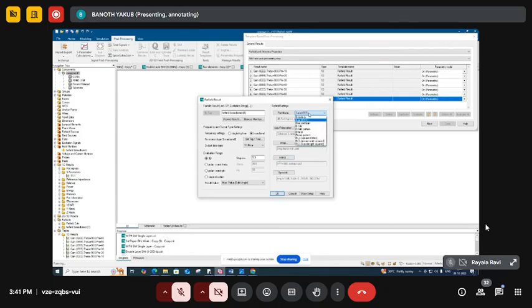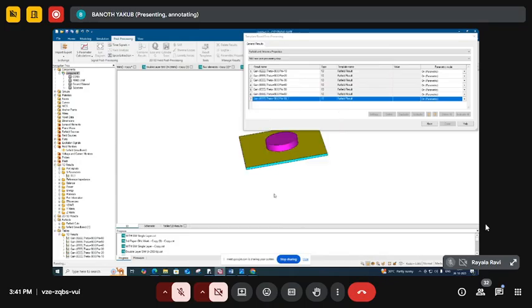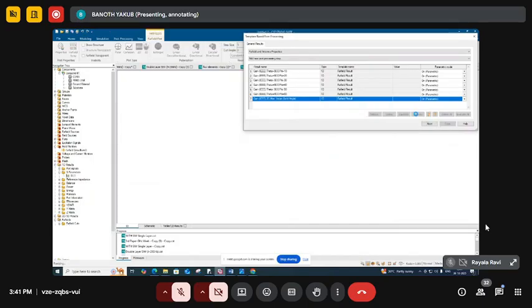The plot mode is gain. For axis and polarization you can select ABS, click on OK, and just click on evaluate the particular gain dimensions results. Just evaluate that. So you can see how much gain we achieved for this particular antenna design, in this particular evaluation process.